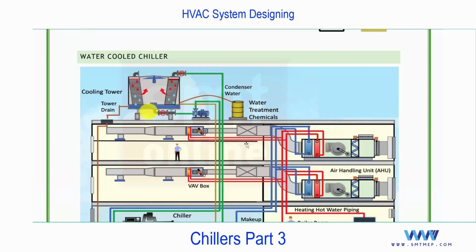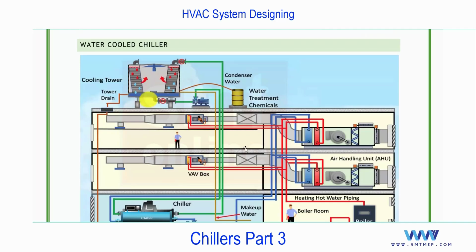Soft water plant is required, a dosing plant. If you are getting hard water in your location, then to convert it into soft water, like 2000 TDS level we can consider as hard water. So to convert that hard water into soft water, a dosing plant or a softener is required. Or else what will happen, the life of the system will reduce. This is also one disadvantage, but we have some more points.